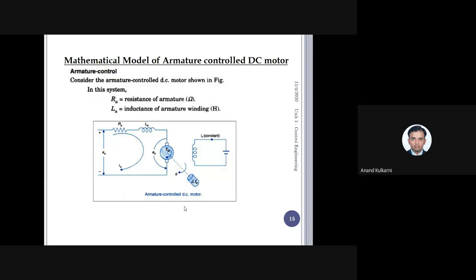rating of the motor. So the basic problem is, if you try to reduce the speed of the motor, the torque will not increase in an AC induction motor, and thereby the power also comes down. Similarly, if you try to increase the speed, the torque reduces at a much faster rate, and hence the power decreases further. So in AC induction motors, in normal cases, by controlling the power supply to the motor, you cannot control the speed. That is the basic drawback of the AC induction motor.